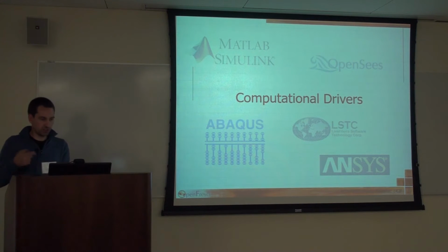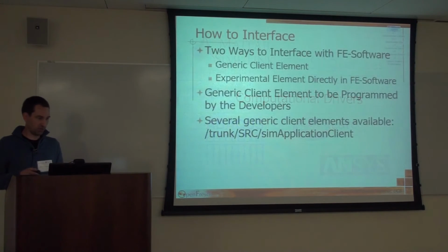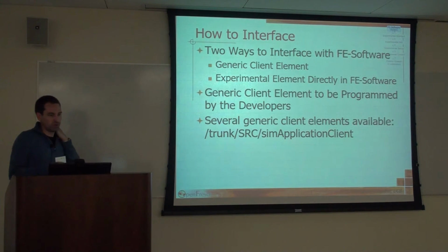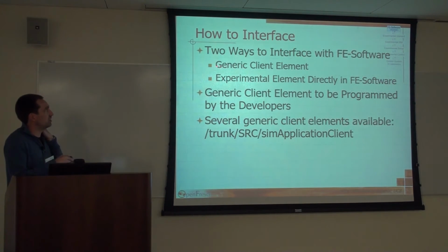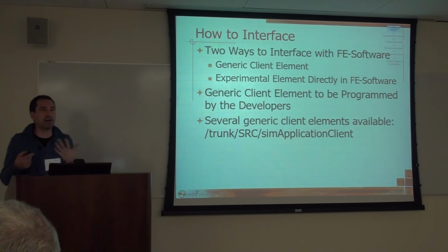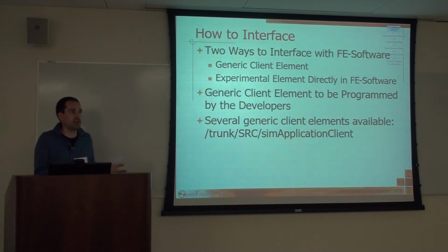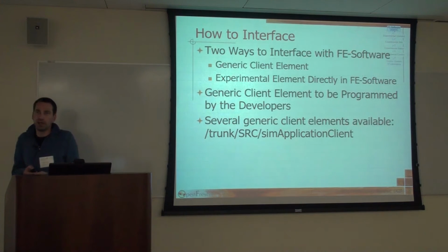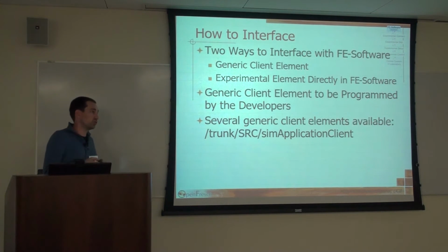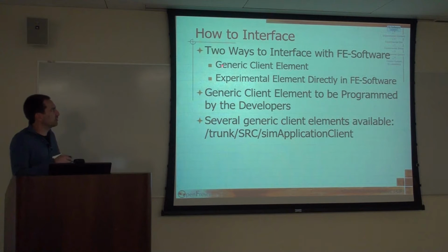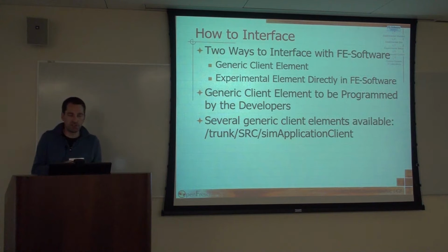I've already touched on it, and Sean has touched on it. We have a lot of computational drivers that we allow to interface with. There are two ways to do that. We can do this through an implementation of a generic client element into any finite element software. So if you have a commercial finite element software that's your favorite, as long as it has an interface to do a user-defined element, you can implement this generic client element into your commercial finite element software.